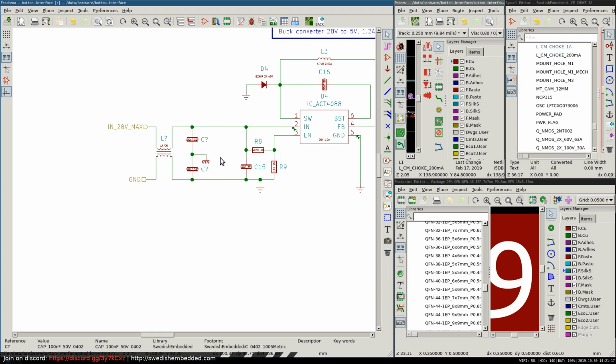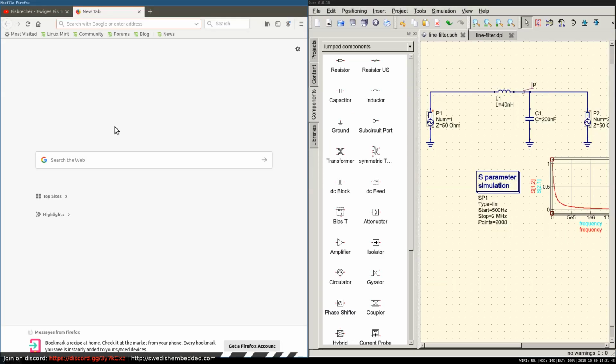So, the next question is, obviously, what should I be filtering? And I've been sort of reading through various materials. Obviously, we have the known frequencies. Oh, there's another thing, by the way. The output impedance of this filter has to be less than 10 times the input impedance of this one. So we have to check the ACT4088. Let's go to the datasheet and check what the input impedance would be on this one, so that we know.